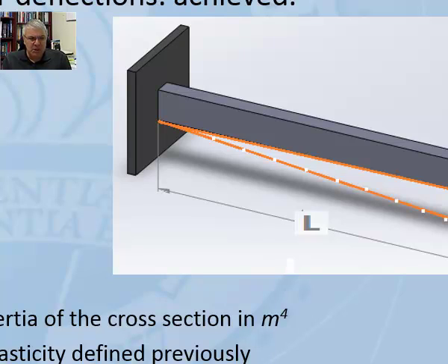The configuration is shown here. Again, the length of the cantilever beam is fixed on, in this case, the left-hand side. Why this bracket is fixed, so that's the assumption there. Of course, the way it's shown here, it may seem that this particular bracket is not going to just fix that, but again, this is connected to other larger pieces that are either welded, in most cases bolted, in such a way that we would have no displacement at one end. That's the definition of a cantilever beam.